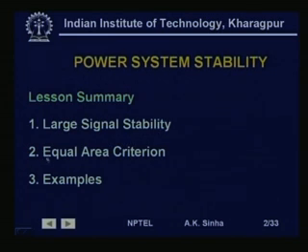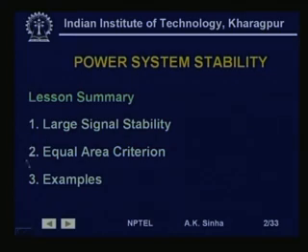We will then go into the equal area criterion method for analyzing the stability of a single machine connected to infinite bus system for large disturbance, and we will take some example to clarify this idea, how we use this equal area criterion.